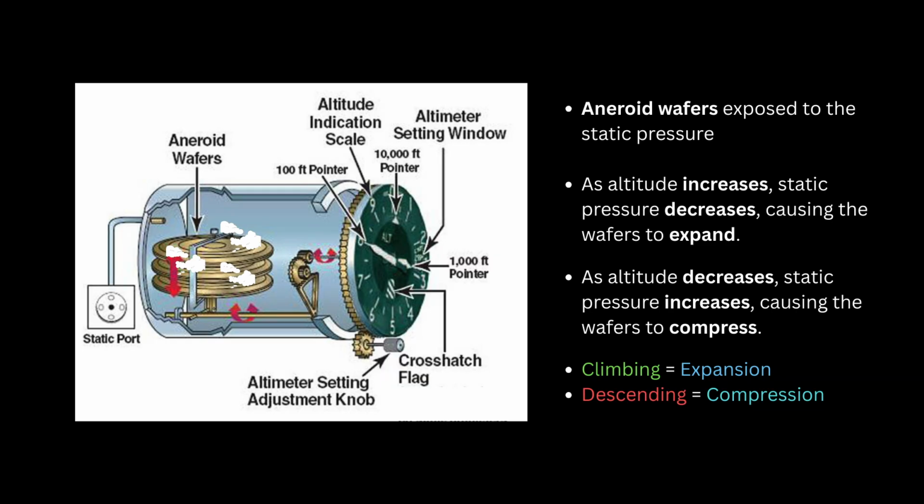As the aneroid wafers in the altimeter expand in a climb, the movement rotates gears and linkages, moving the needles to the right or upward. The opposite is true during a descent.